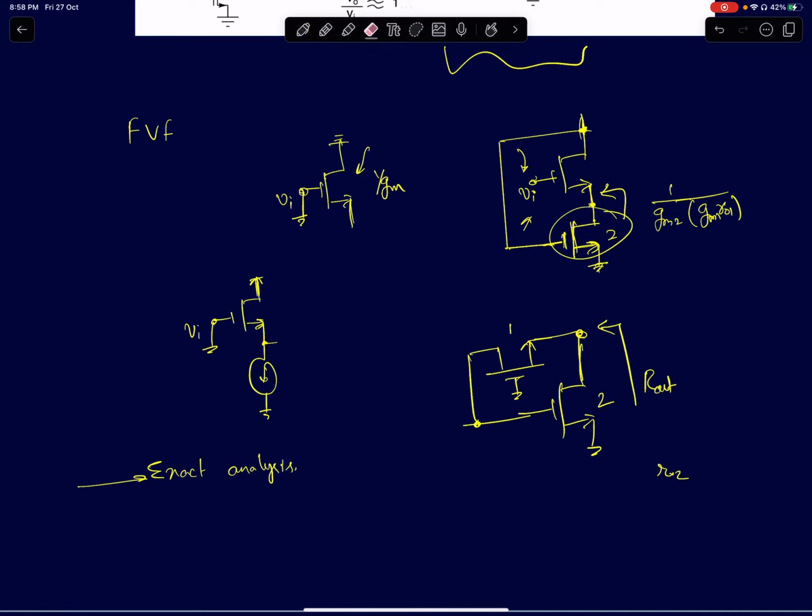In the presence of negative feedback, if you apply a test voltage Vt, what would happen is that this is like a common gate amplifier, and the DC gain of a common gate amplifier with open load, your load is infinity. Okay, it's going into the gate of the device, which is infinite impedance, is 1 plus GM1 RO1.